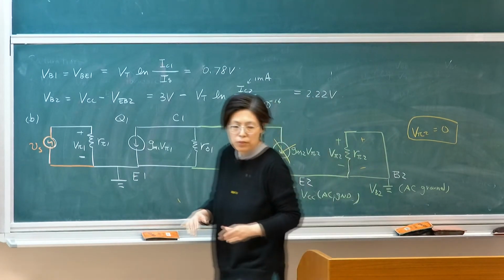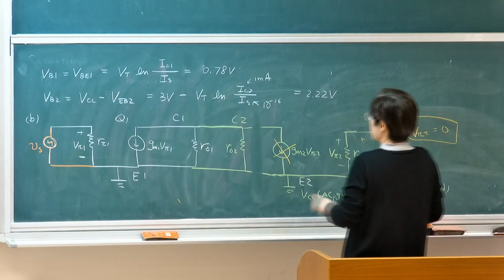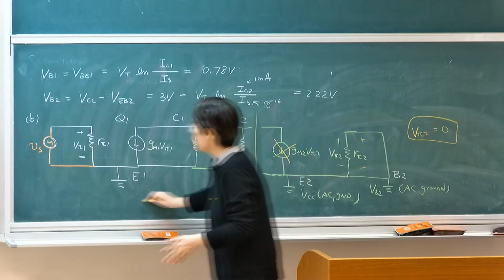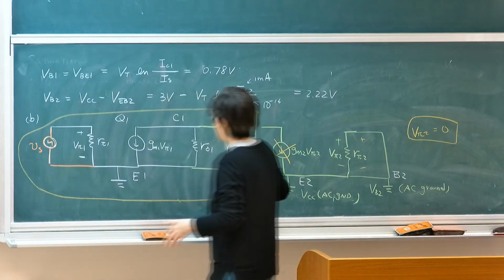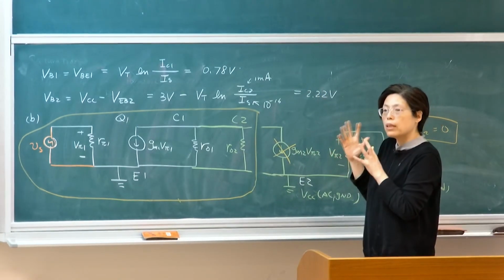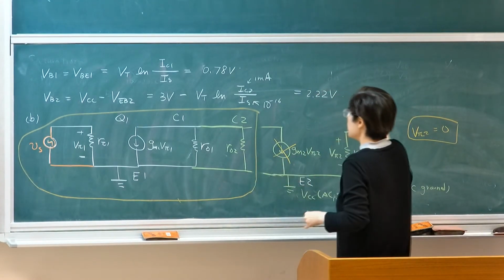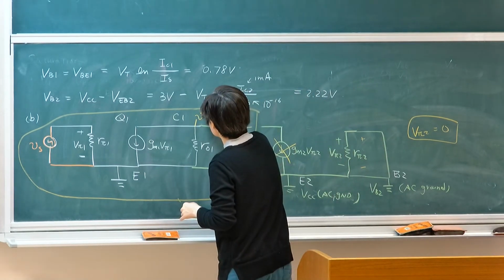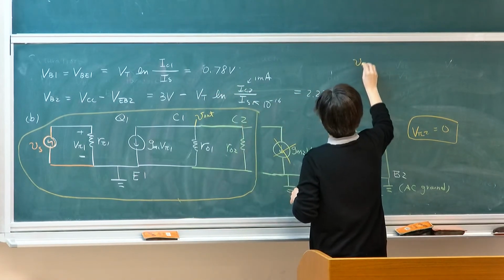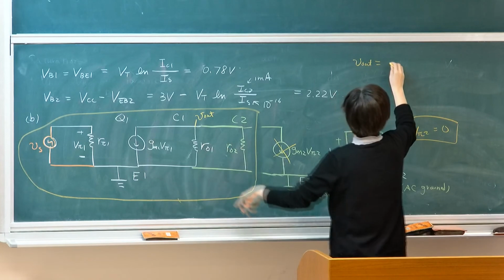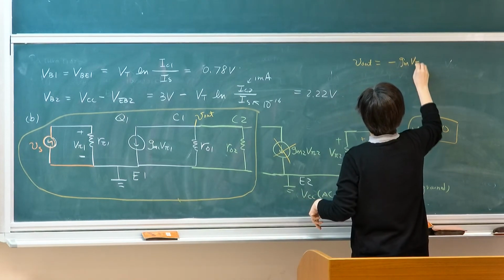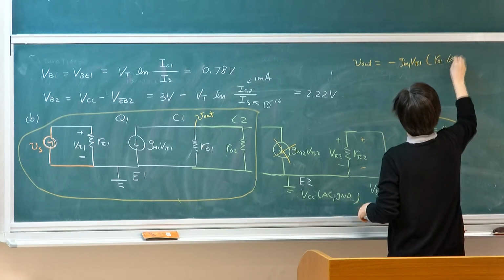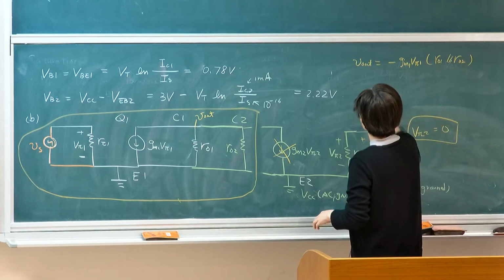So when we look at this circuit, we can very quickly get our output response based on this part, because the right-hand side only contributes RO2. The PMOS load only contributes RO2. So you would then get your output. This common node is my output. So my VL will then become current, which is minus GM1 V pi 1 times RO1 in parallel RO2.